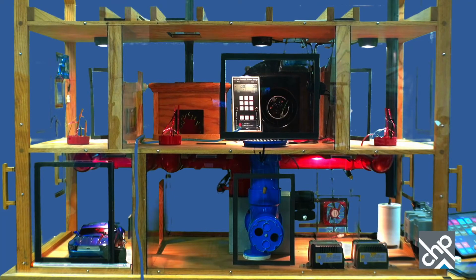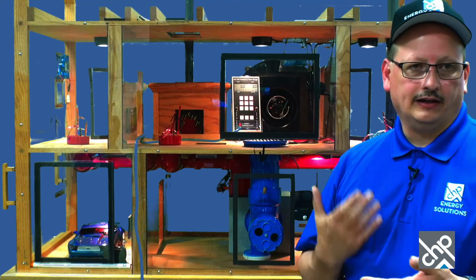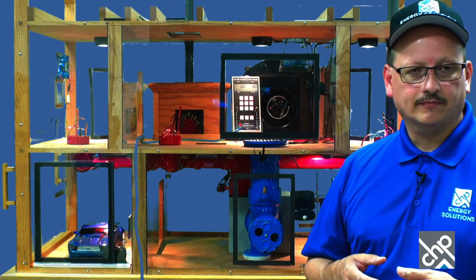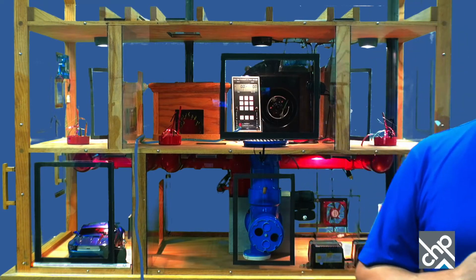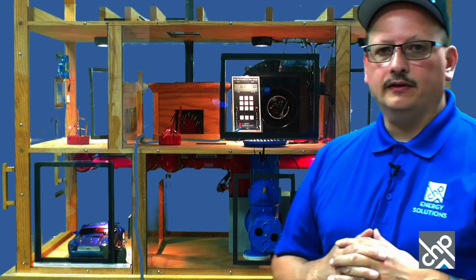Right, so I've got everything back off here now, and as you saw, kitchen exhaust or bathroom exhaust fans, and then we saw duct leakage. And when you do that duct leakage, it's actually a test called the dominant duct leak test. And the dominant duct leak test is basically you set up the manometer like I showed you before. You do a baseline test. All your interior doors are open just like you would for a blower door, kind of like natural conditions, or some people call it winter conditions. And then the only thing that you're turning on is the air handler fan. And you're going to notice the pressure change between indoors and outdoors.